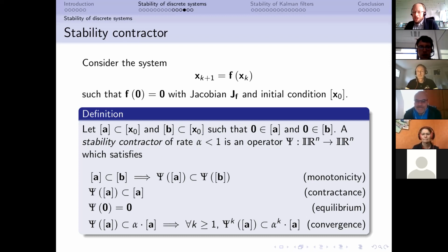Because for linear dynamic systems, you just give person A the task to design the controller, person B designs the observer or the Kalman filter, you plug both together and it will work. In the nonlinear case, you may induce unstable behavior just due to the fact that the interconnection of two stable systems leads to something that is unstable. Absolutely. Yes, these were the philosophical comments from my point of view.